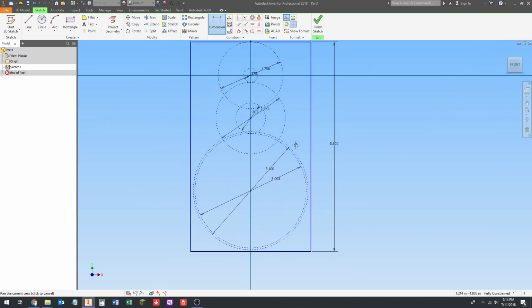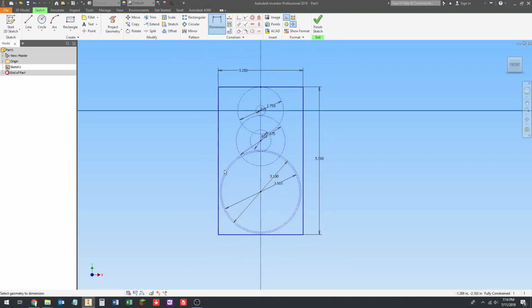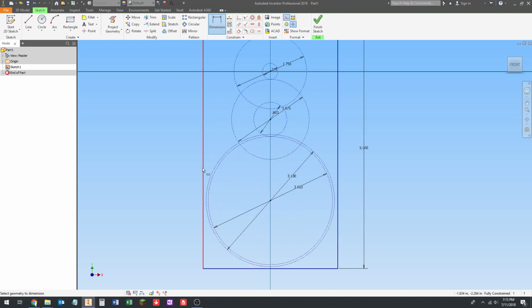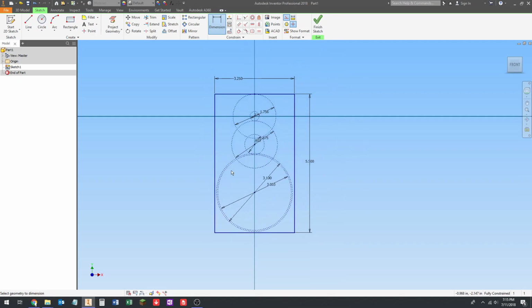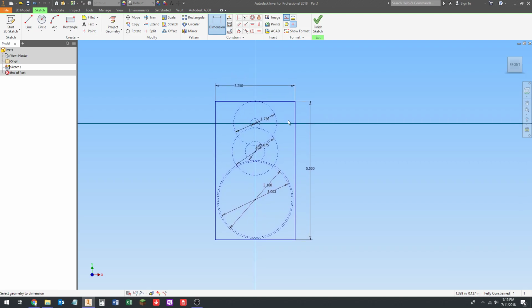Basically, depending on what you're doing on the robot, you might not need the gear to be completely contained inside the plate. You could cut down the plate to save weight, but you have to make sure that stuff can't get caught in the gears, and you want to have a little bit of containment for grease and such. Typically it's common practice to cover the profile of the gear with a plate, but you end up putting lightning holes in it. So that's really just up to the designer. In this case, to make it simple, we're going to make this plate this size.